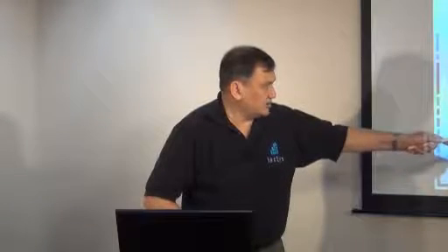But now look at this in a little more depth. It says for both pre-contingency, which is the state of the system right now, or post-contingency, which is after an event has happened. So really, there's no way you can look at what will happen on a complex power system without running a detailed simulation with a model. So in the post-contingent state, all of these ratings have to have models which the operator can run and determine: is the system running within the operating criteria?